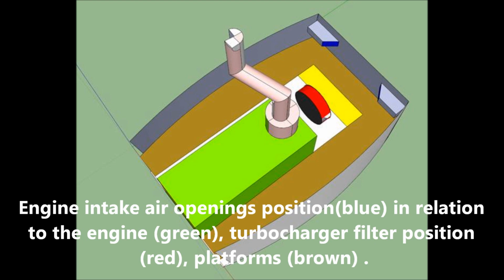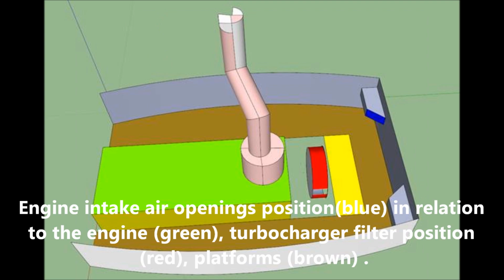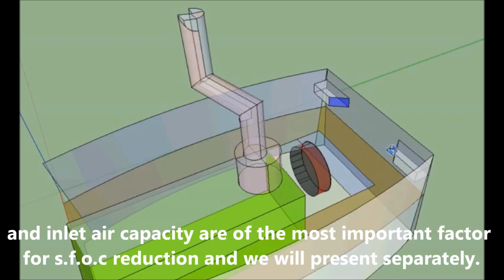Engine intake air openings position, blue, in relation to the engine, green, turbocharger filter position, red, platforms, brown, and inlet air capacity are among the most important factors for specific fuel oil consumption reduction, and we will present them separately.